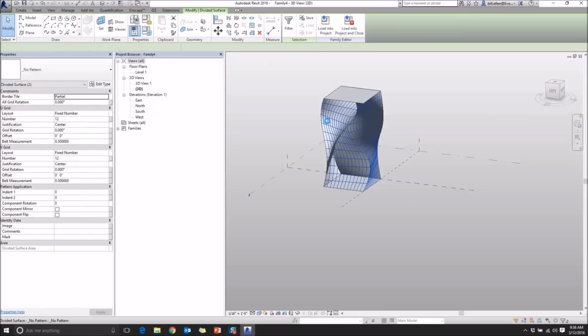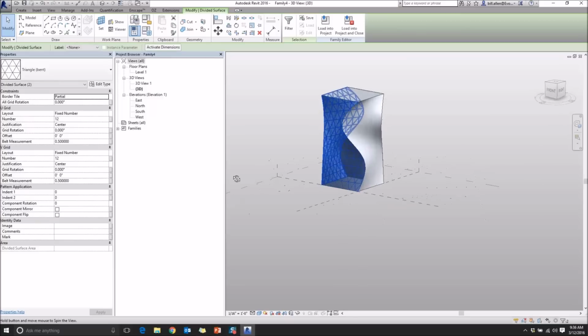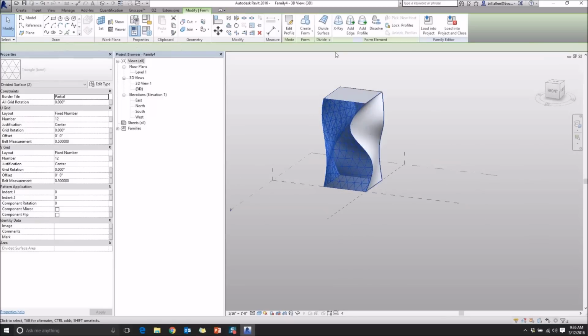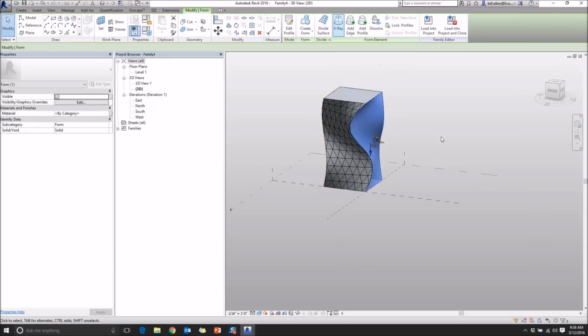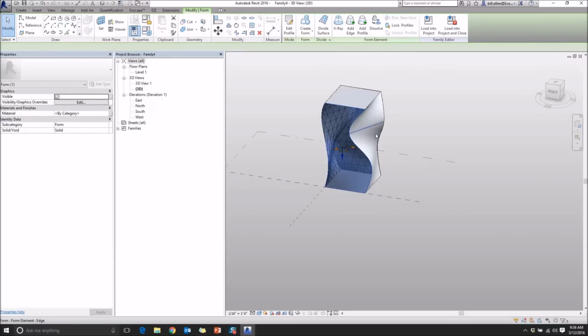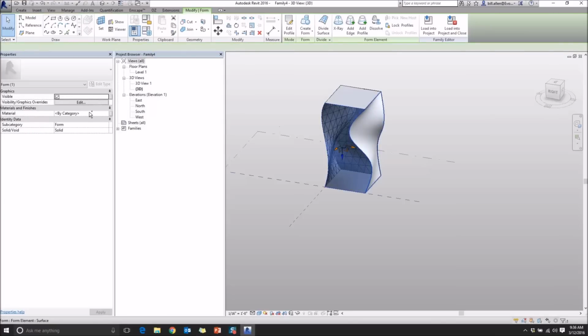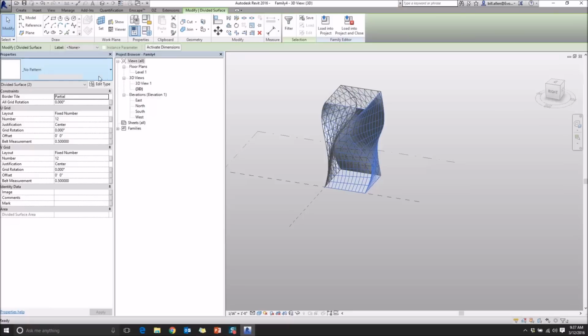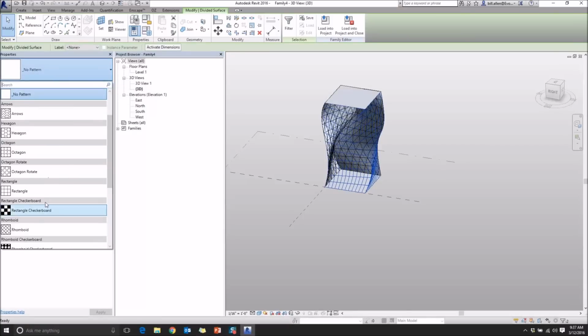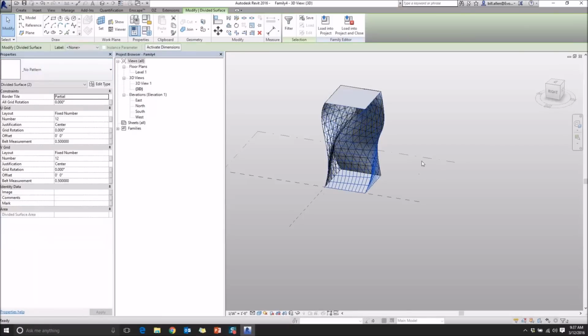These are really good for making sure that your geometry is planar. Triangles are always really helpful with working some of that out. And I'm just going to do the same over here. Make sure you pick the face, say divide surface, and I'm going to pick that triangle again,